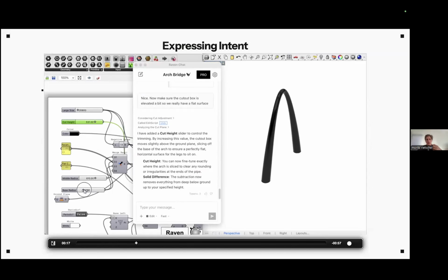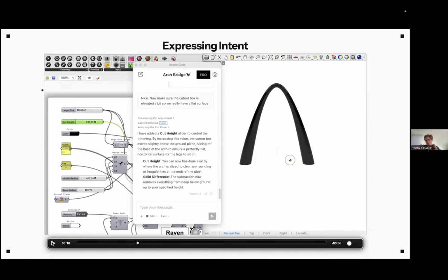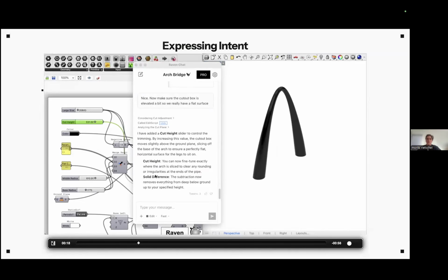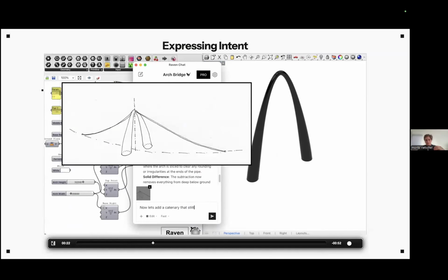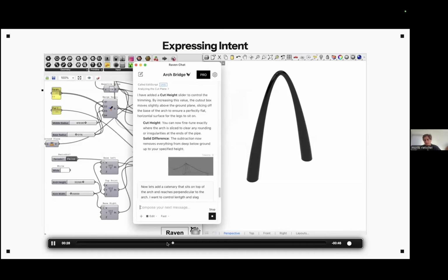I can adjust them, even in this case, just visually, explore thicknesses and so on. It's in a way that normal CAD currently really doesn't allow you to do, because you have to define everything. With Grasshopper and parametric design in general, you can be way more loose, which we think is super interesting for earlier parts of the design process. So if you're making something, you don't have to make one rigid Rhino model, but you can actually make these parametric and living models instead. I think that's really compelling.